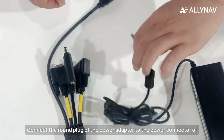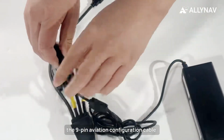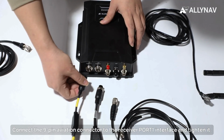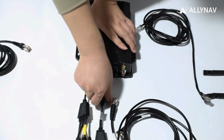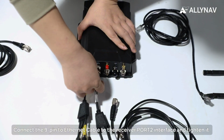Connect the round plug of the power adapter to the power connector of the 9-pin aviation configuration cable. Connect the 9-pin aviation connector to the receiver port 1 interface and tighten it. Connect the 9-pin to Ethernet cable to the receiver port 2 interface and tighten it.